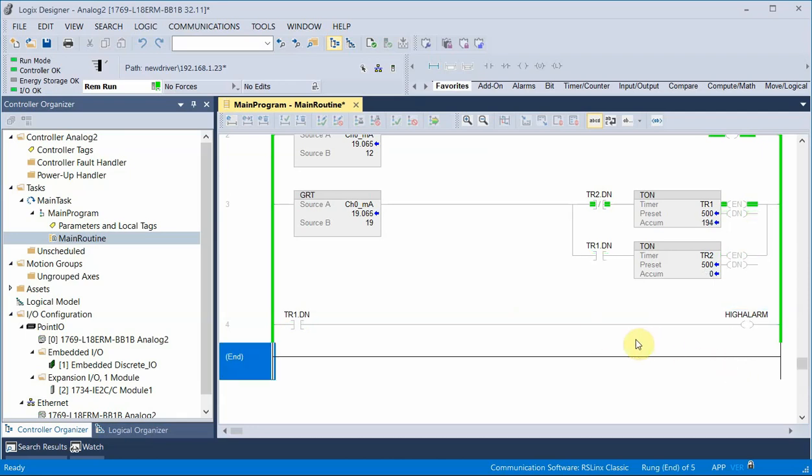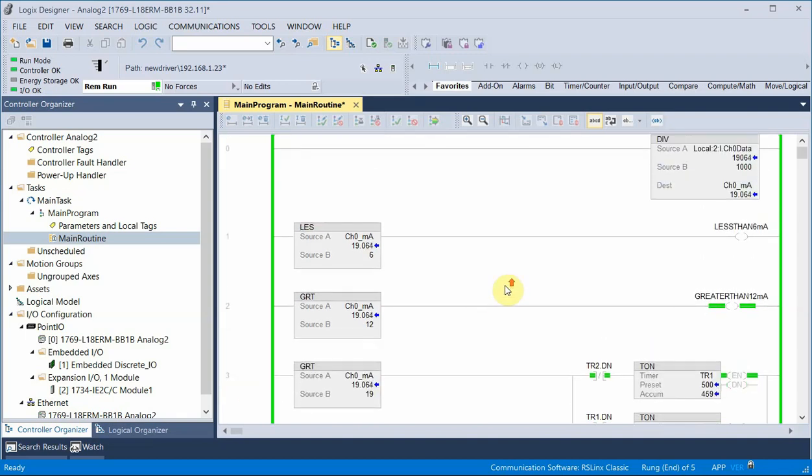So, really a milliamp signal is coming from a transducer. It's either temperature, pressure, level, tank level. It could be almost anything. Distance could be distance as well. And I'm going to turn that raw number into a scaled value. Here I'm looking at straight milliamps.